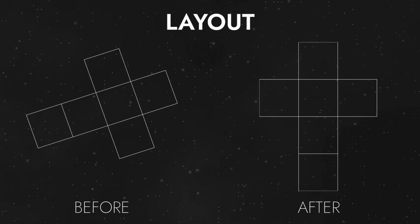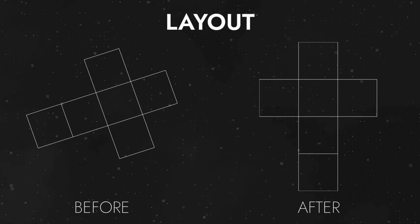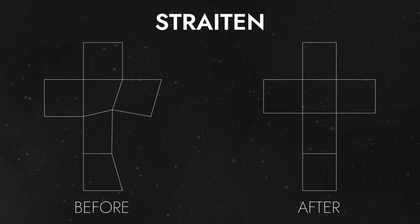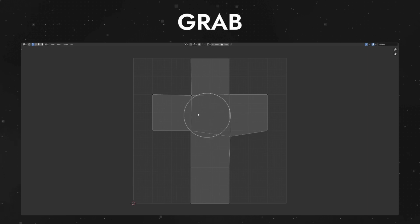Layout. This command automatically arranges UV islands within the UV square. It also has several settings that can be useful for you, so check them out. Straighten. As you can guess, it straightens your UVs. Grab. Allows you to grab and pull UVs.